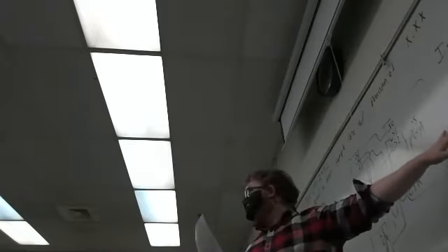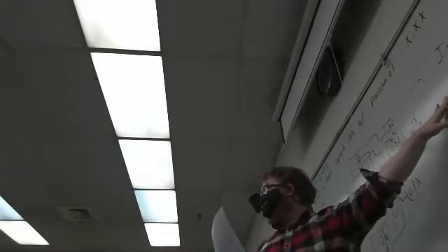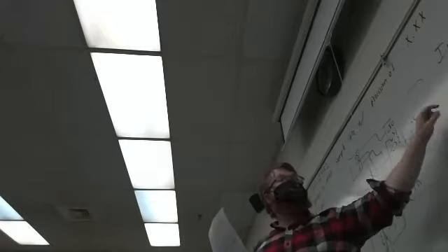It is no longer using any of the CSs, so we get rid of all of those. But now I have to write data, so depending on how it goes, we could have a single data line that is an IO, or data in, data out, and a clock. So I'd have one IO and one out.